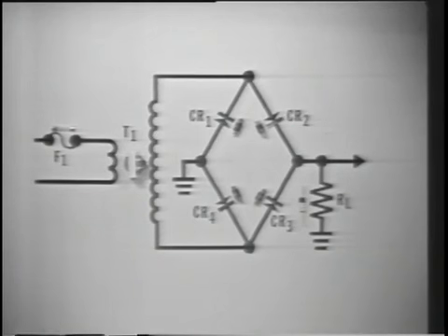When troubleshooting and the symptom is no output, look for trouble in one of the common components. If the symptom is only half-wave output, it's probably caused by an open diode. And there you have it, the solid-state bridge rectifier. Now later on in the course you will study the vacuum tube bridge rectifier. Confidentially, they both work exactly the same.